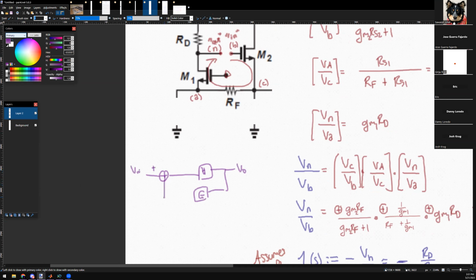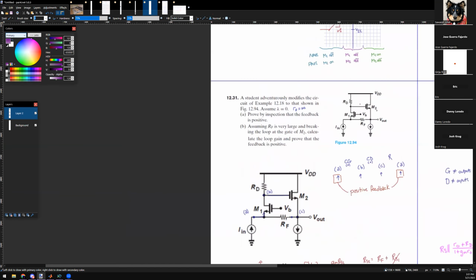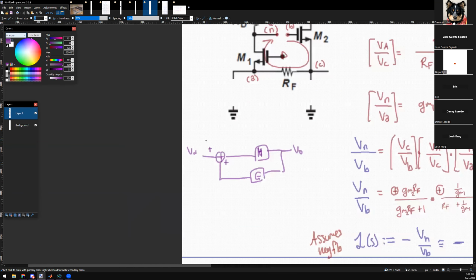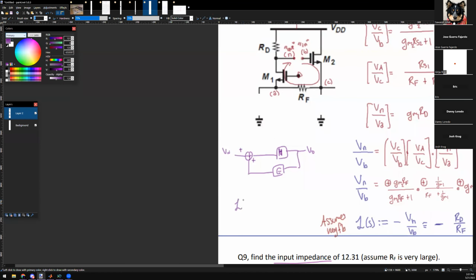And when you solve this, it was actually a plus here. And that's positive feedback. You agree? That was our initial thing, right? That's how we found that this guy's positive feedback. So this guy has this type of block diagram. You have a forward loop and you have a feedback resistor, right? But by convention, when you write the word L of S, it assumes negative feedback.